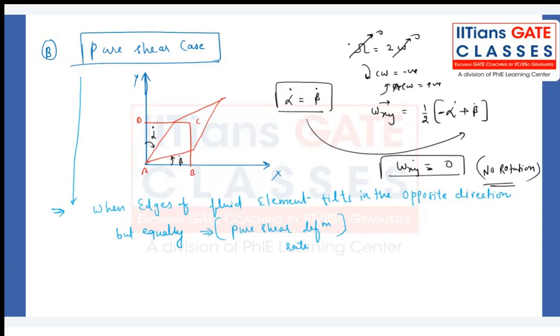Like inviscid flow, here what you are observing, whether this is a viscid flow or inviscid flow, tell me. At least some deformations are happening. So you might be tempted to think that, sir, this is giving me some shear force, because shear force we can write as mu times alpha dot plus beta dot times area, right? And here alpha dot and beta dot both exist.